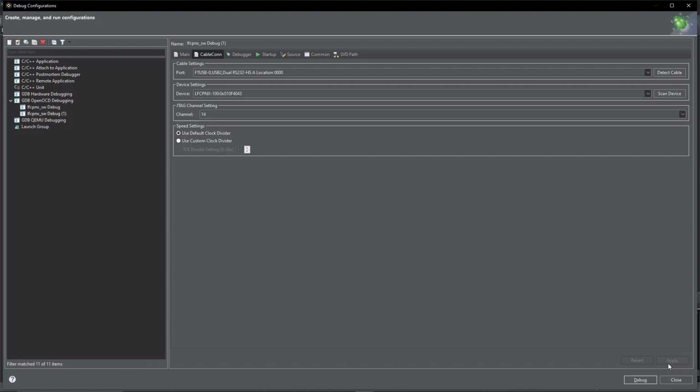However, if there are some issues, you should ensure that your JTAG connection is not actively being used for something else, like programming or debugging with Reveal. Otherwise, you may see no device here, or a plus icon instead. If the issue persists, try changing the TCK clock divider setting to slow down your JTAG clock frequency, or power cycle your device and attempt to reprogram it.